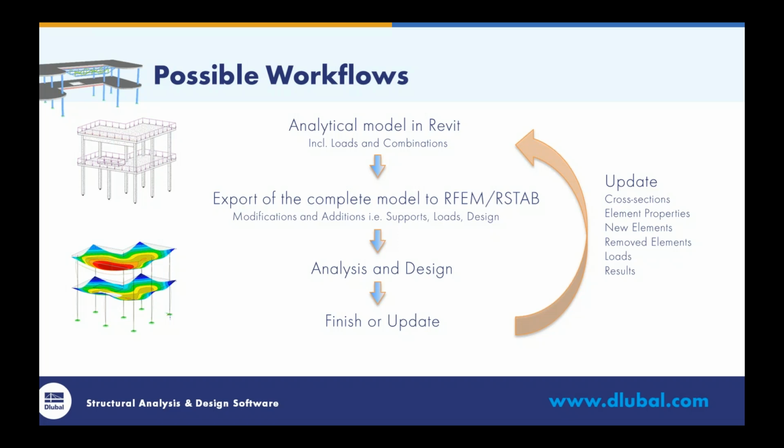In RFEM, you can continue, you can modify the structure, you can add supports, you can add member hinges, loads, you can combine the load cases, and of course, you want to run the analysis and the design. If everything works out well, you can finish your design, you can create a protocol, and you're done.